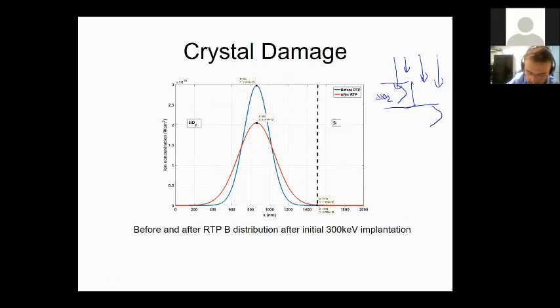The blue one is showing you right after the implantation, the Gaussian distribution inside the silicon dioxide. You see, this is the silicon and silicon dioxide interface. Right after this, we have to put the whole thing into annealing, because we'd like to repair the crystal. There's too much damage here on the crystal.